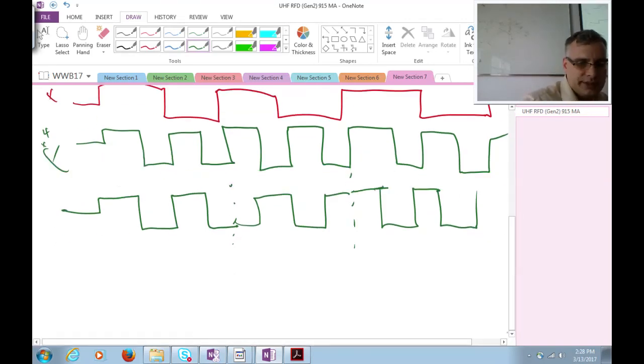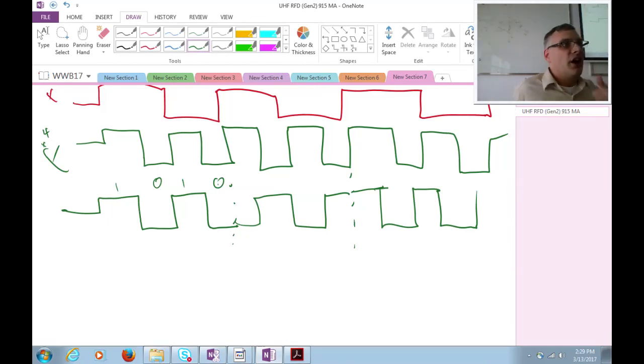Spectrally, what is that doing? Well, remember, now I have to transmit or transition multiple times per bit period, which means I'm adding transitions per bit. If I view this as coded data, I have 1, 0, 1, 0, and that's just to transmit one bit. So now back to the case of I'm increasing the transitions per bit, which means I'm increasing power consumption. My joules per bit is going up that I'm using to send data across my link.